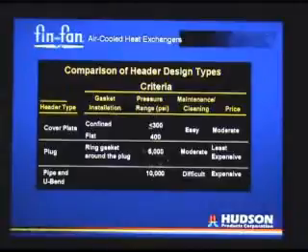This shows you an example of the various types of pressures and selecting the type of cover or tube sheet that you would want to deal with. Plug sheets have gone up to 5,000 psi. Usually on these designs you would also have an internal seal weld to ensure a good mechanical joint between the tube and the header.